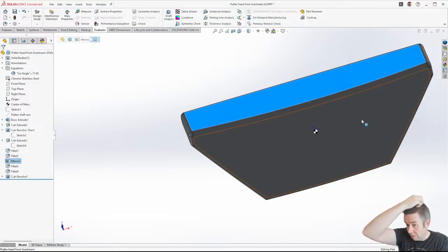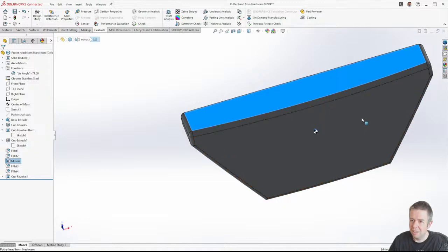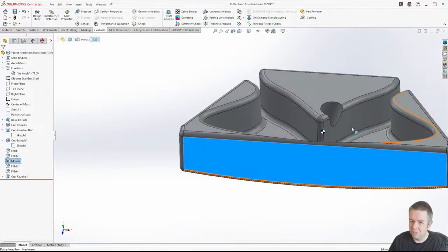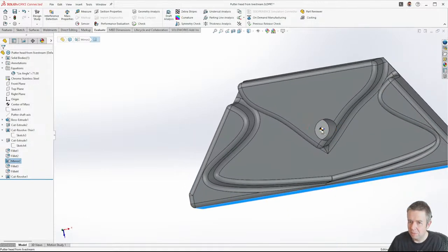So what that will mean is we can put different weights or lengths of screw that weigh different amounts into those screw holes in order to manipulate the center of mass in a relatively subtle way to correct for any machining errors so that it does remain balanced around that point.